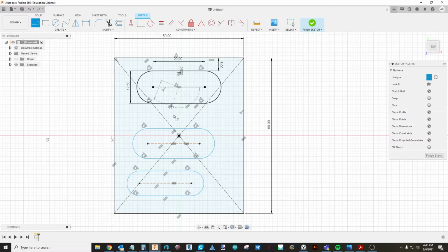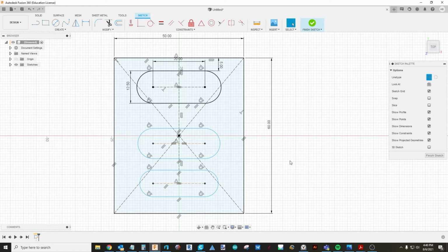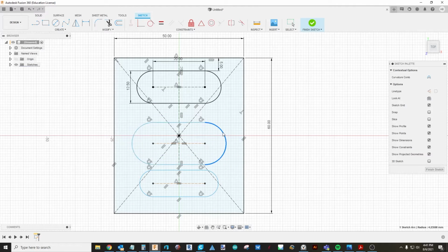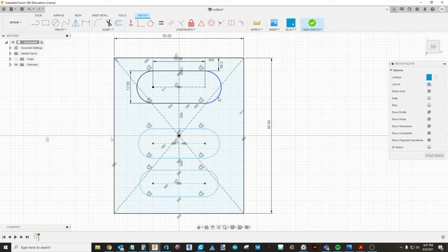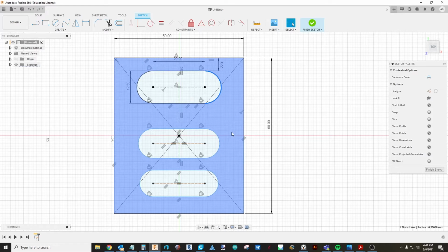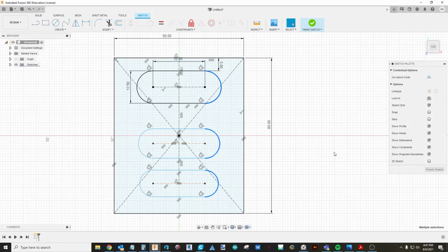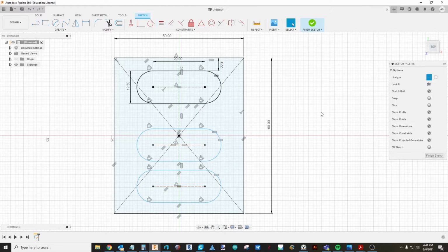I'm going to do a similar thing for these, since I want all of these pill slots to be in the middle. So here's my midpoint to midpoint line, and then midpoint to midpoint line. I'm going to apply that same constraint to these. So now you can see they're all in the middle. So I believe these guys are still unconstrained this way, but I'm going to select this arc, this arc and this arc. I'm going to tell all those arcs to be the same. So I'm setting their radiuses equal to each other. So now they're constrained, and I can't change that anymore.